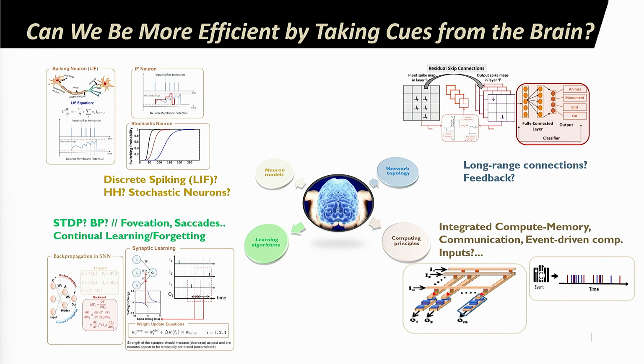They're all integrated together in some interesting ways. So the question then is, is it possible that I can do some compute-in-memory kind of computations and get efficiency? Because in today's von Neumann architecture, one of the problems that we face is that we have to fetch data from the memory, bring it to the compute unit, do the computations, and then bring it back to the memory again.